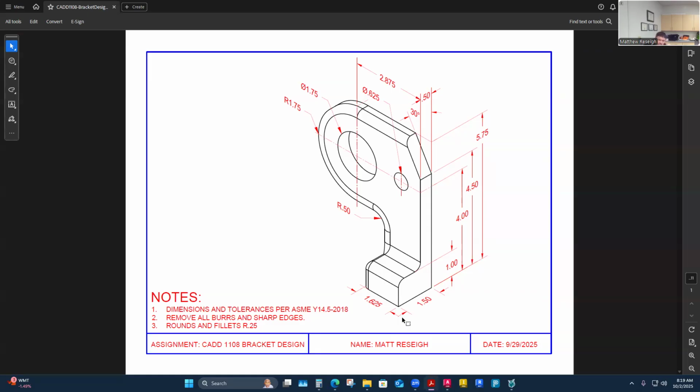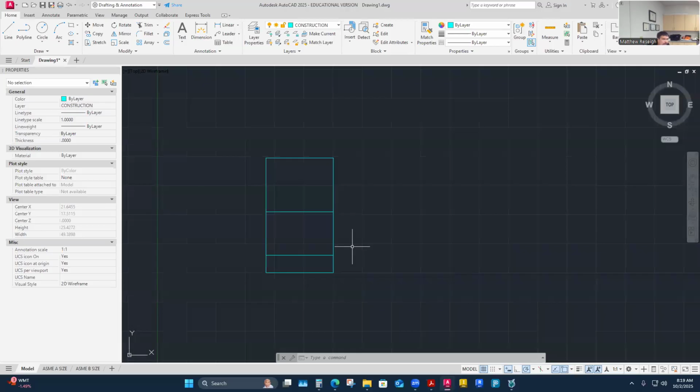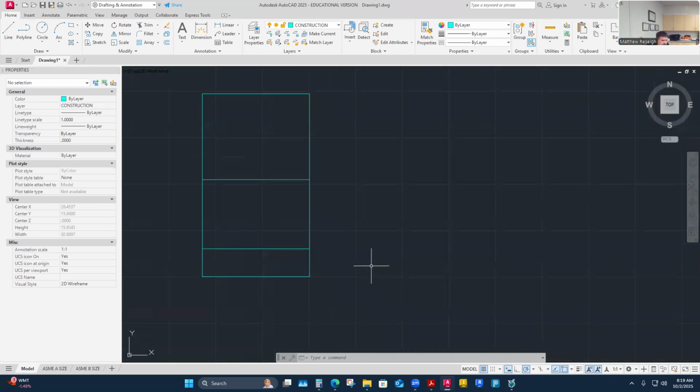But I'll go ahead and box it in right now, and I'll decide that as I build out the front and top. For sure, my front and top I'm going to build out, and then I'll decide what I feel like I'm lacking from those, and if I need it in my right side view. I know when I've done this in the past, and I've done it out of position, I think I did three views of it, and I did use all three views for dimensioning. So I can't say till I get there if I really need it.